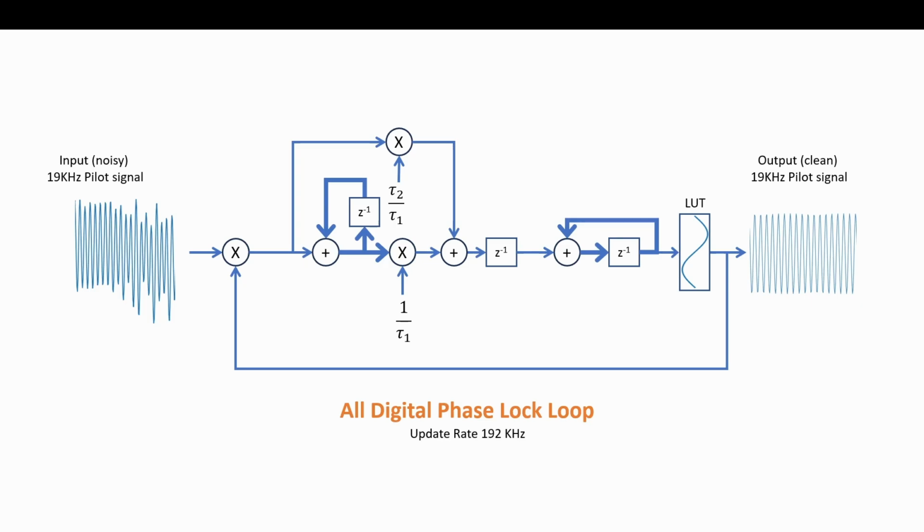The multiplier is a way to make a phase detector. You multiply in frequency, it adds and subtracts. The difference will be the phase itself. By the way, you can use an XOR gate as a phase detector. An XOR gate is a multiplier of two square waves. An XOR gate is a nice phase detector if you're stuck needing one without a lot of stuff. But a simple multiplier is a phase detector.